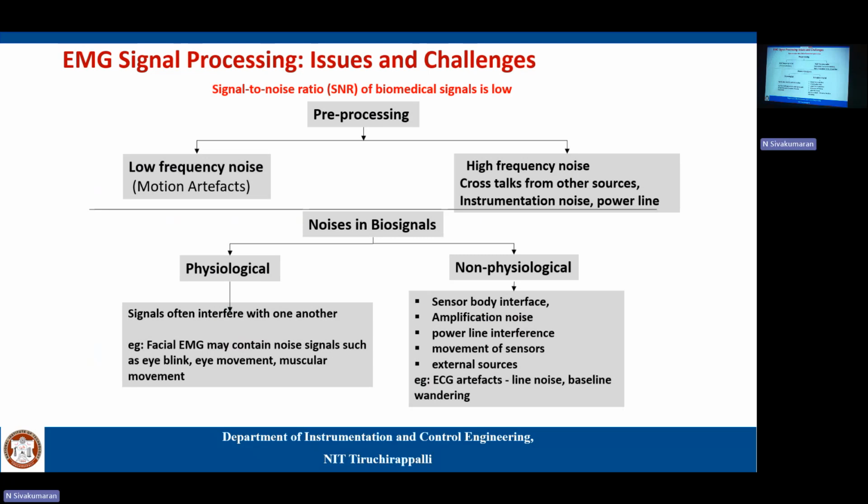Okay, up to some limit we can control. So pre-processing: generally, when we do pre-processing, we will see what all the noises are, particularly when we do online signal processing. Ottobock's EMG-based myoelectric control has come up, which means they have to collect EMG, do all the cleaning, decode the signal, and then actuate their motor. All of that should be done within some 300 milliseconds. That's what we pay a lot of money for.